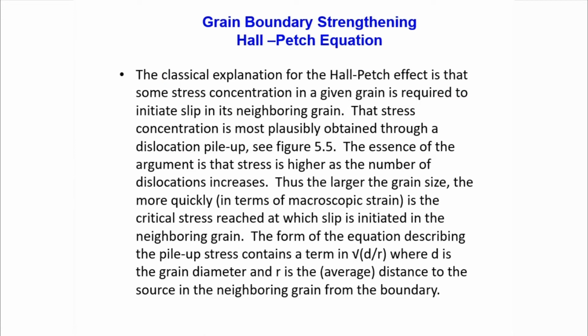The stress concentration in a given grain is required to initiate slip in the neighboring grain, and this leads to pile up, that is shown in the last figure. The essence of the argument is that the stress is higher as the number of dislocations increases. So, stress will be much higher as the dislocation pile up increases, right. As the size goes down, the number of dislocations inside the grain goes down, and at a particular grain size, only one dislocation can be accommodated inside the grain, and the Hall-Petch mechanism breaks down.